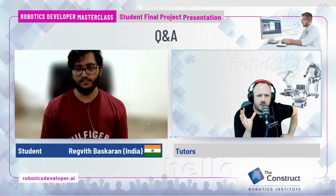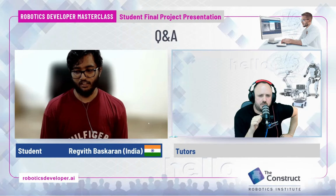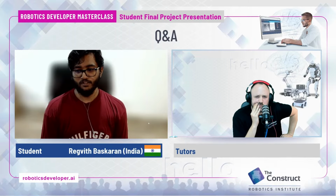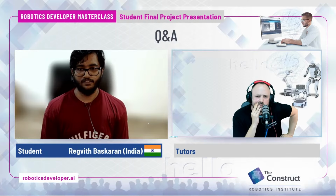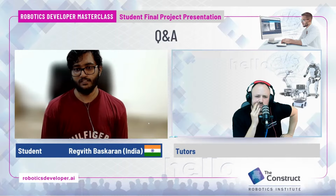No, actually, what I do is calculate the center. I accumulate all the points and I've put a seeding for that. It needs to find a particular position in between all these points so that it's reachable to all the positions that are there. How I've calculated it was using the average mean method, and I publish that specific point in XYZ and set the goal pose target. Then it goes to that particular middle location, and from there on it starts to go towards the other holes.